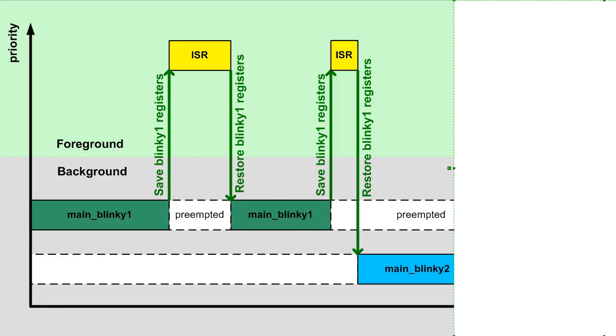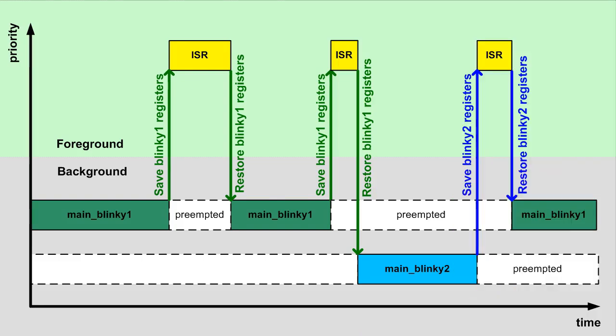However, when you manually modify the return address, you are returning to the Blinky2 thread, but you still restore the registers saved originally for the Blinky1 thread, which is exactly the illegal part. It happens to just work for the dead simple Blinky threads, but it can and will break down for more complex threads that use more registers.